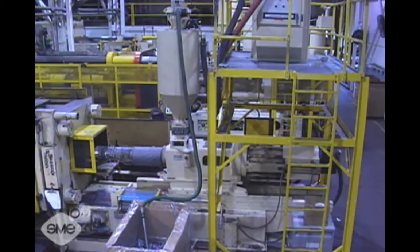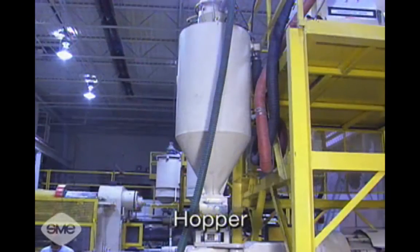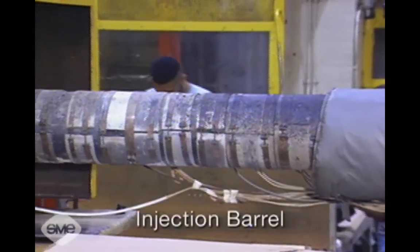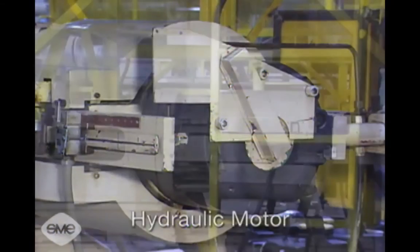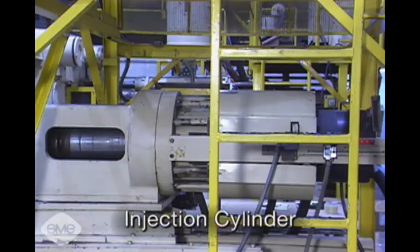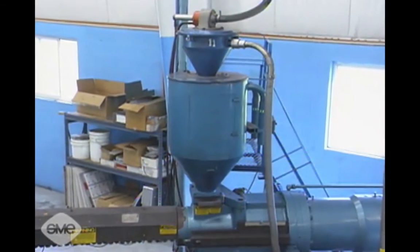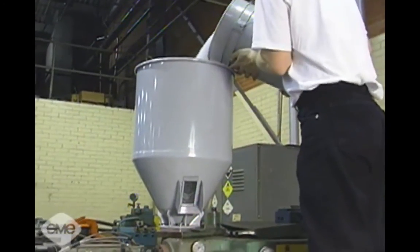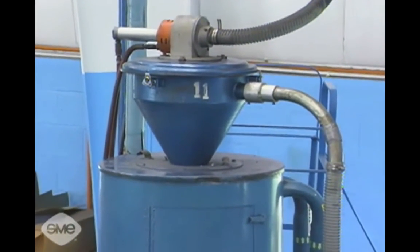The main parts of the reciprocating screw injection system are the hopper, a reciprocating screw inside an externally heated injection barrel, a hydraulic motor, and an injection cylinder. Resin material is fed to the injection barrel from the hopper. These hoppers may be filled manually or vacuum-fed automatically, and often have dryers attached to the top to remove the